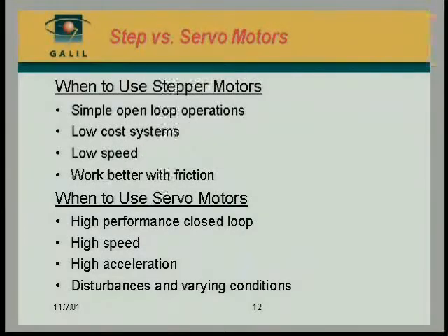A stepper motor, you should consider if you have simple open loop operations. If you need to drive something over a distance, the operation is simple, doesn't have to be very precise, and if occasionally it stopped and failed, it's not the end of the world. In that case, that would be a good solution. Also, if you're really pushing for low cost, that may be one solution.